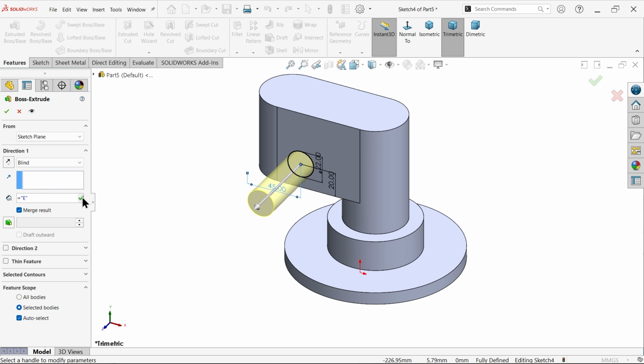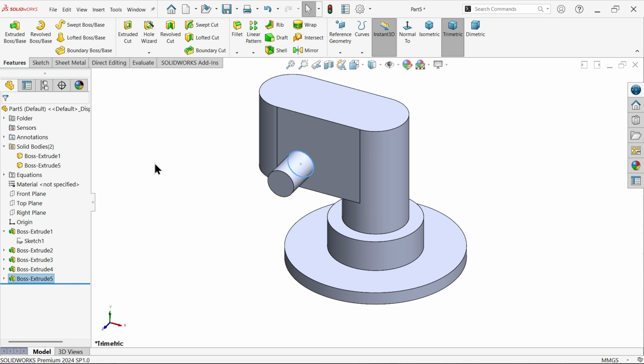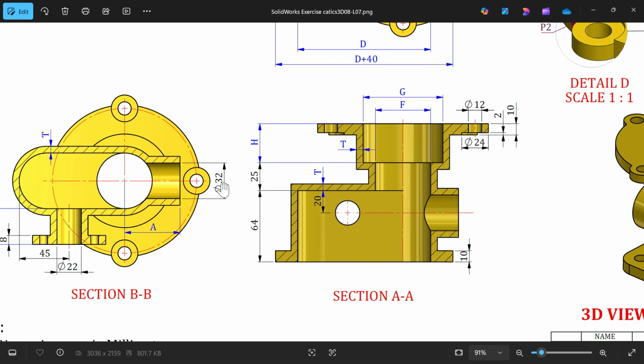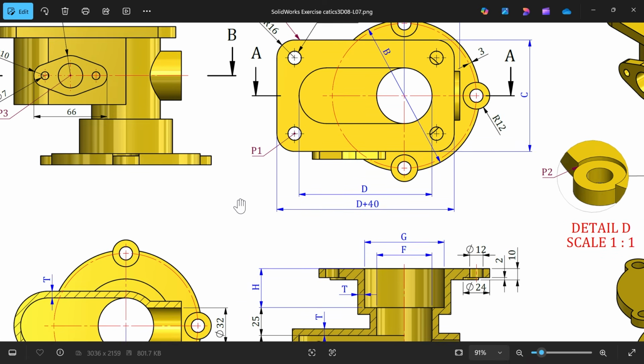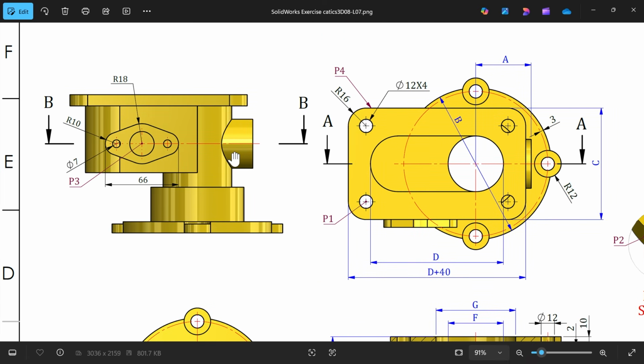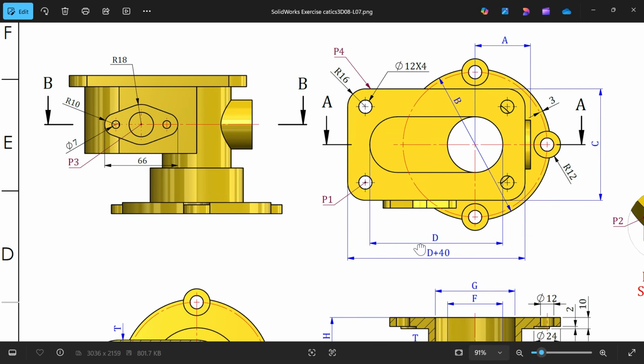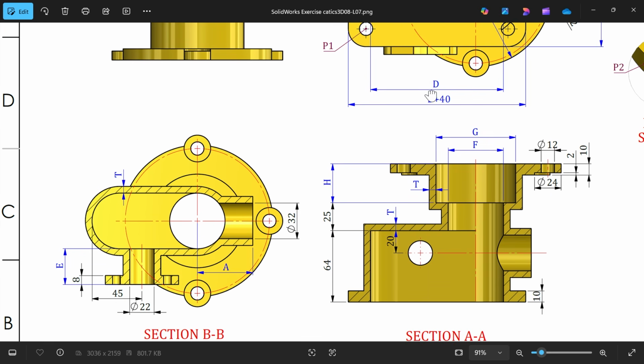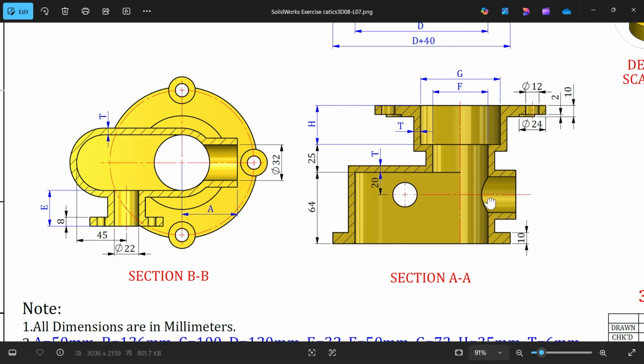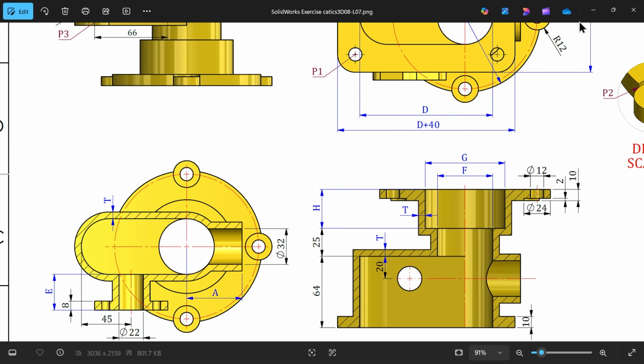Okay. Say yes. Okay. Now let's see this internal depth diameter 32, distance from here center to here A, and location. Okay, this is parallel to this hole. So simply I am going to do this, and this one D plus 40, and this is going to be C, and depth. Where do you find this depth? Okay, depth here 10 millimeter. Fine.